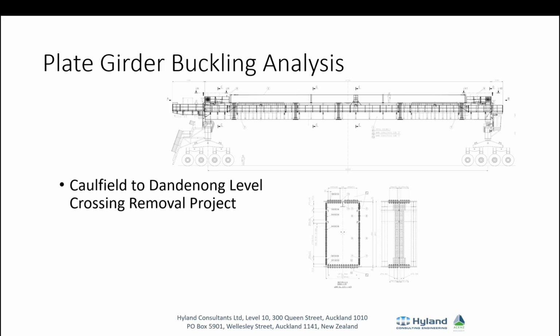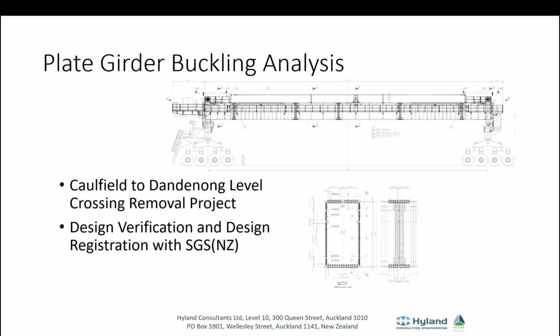It's the Caulfield to Dandenong level crossing removal project, and there's just over 2 kilometres of elevated viaducts, 40-metre spans made of post-tension concrete box girders, and we work for DL, who have designed and manufactured the bridge construction equipment pictured in the slide.